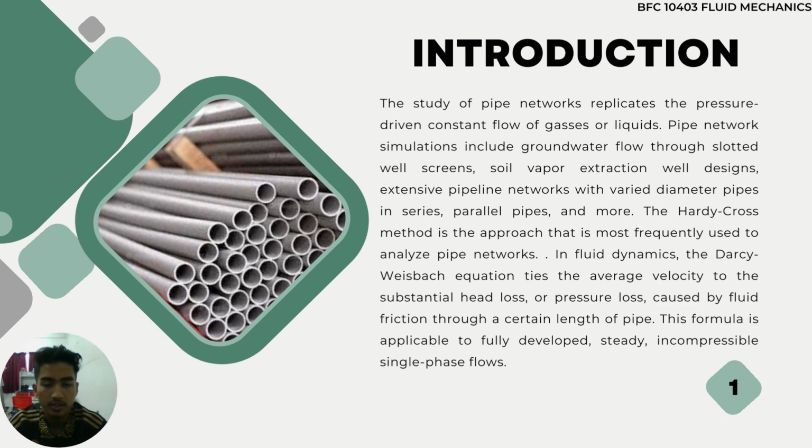In fluid dynamics, the Darcy-Weisbach equation ties the average velocity to the substantial head loss or pressure loss caused by fluid friction through a certain length of a pipe. This formula is applicable to fully developed steady incompressible single-phase flows.